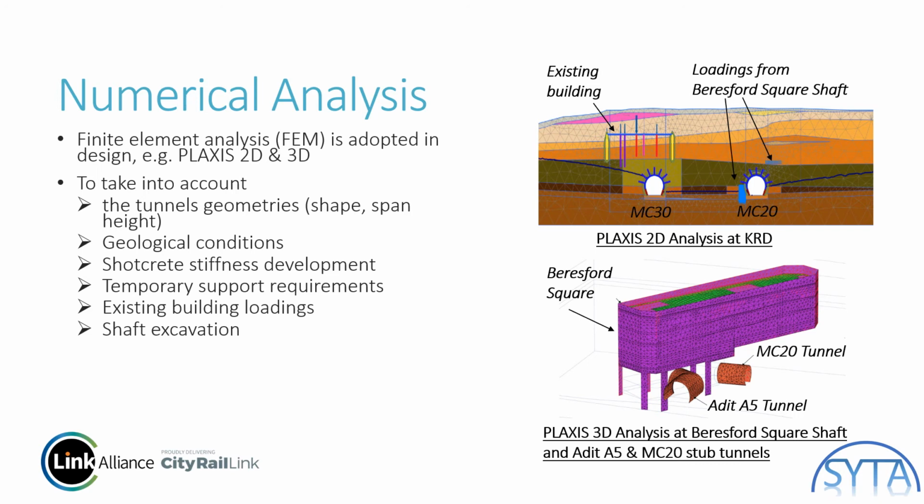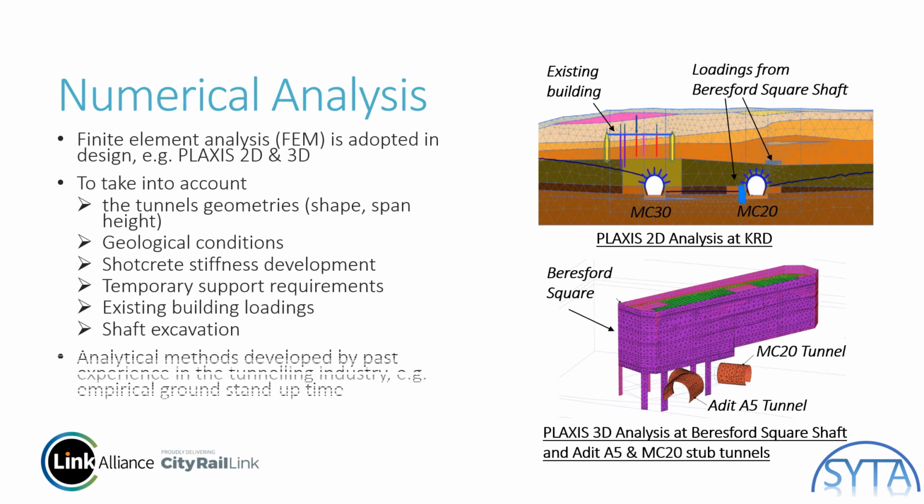On the right-hand side, the figure shows the Belfast Square and the tunnel excavations relationship. This is quite important to our project because the shaft excavation is concurrent with the tunnel excavation. Therefore, we need to know the relationship in terms of stress and loadings to each other. Of course, we also apply the analytical methods developed from past experience in the tunneling industry, such as the empirical ground stand-up time.